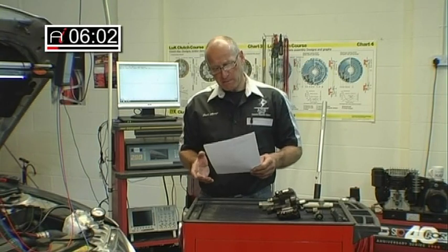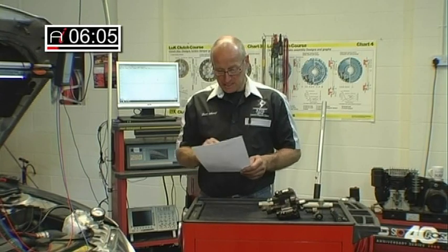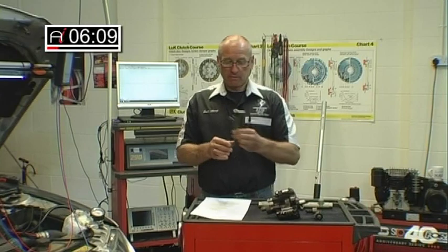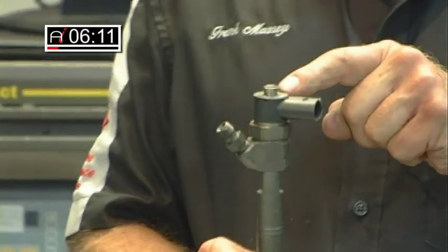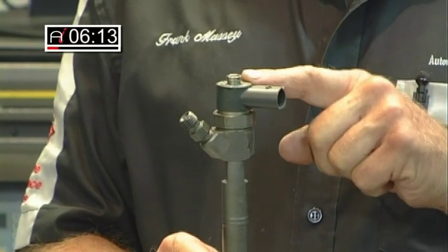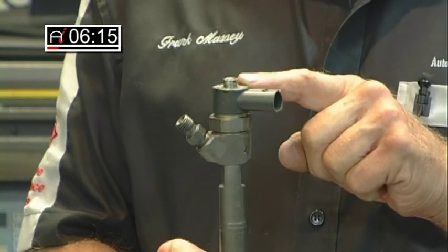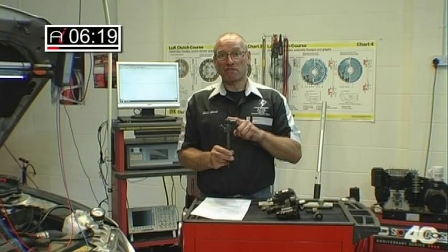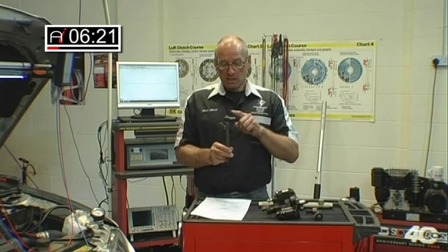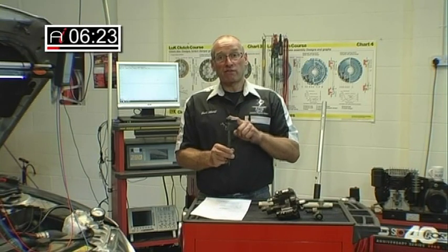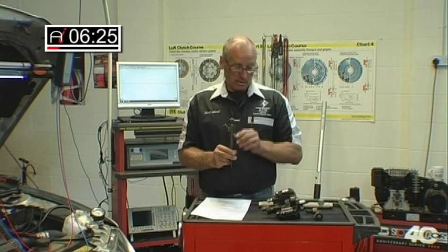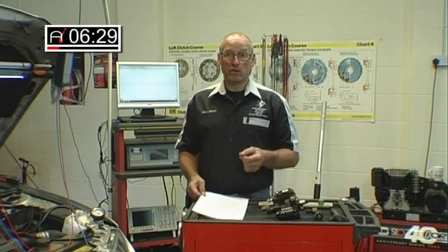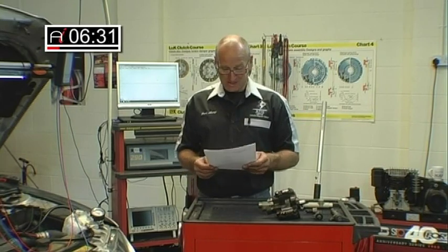rather complex, overpowering statement is trying to explain is that the capacitor which drives the injectors, the operation coil here, is power driven by discharging a capacitor. The capacitor is mounted in the ECU. If that capacitor fails in any way, the injector will not be opened and therefore the vehicle will not run. So it would satisfy the conditions which we are expecting, a no-run condition. So that is one possibility.